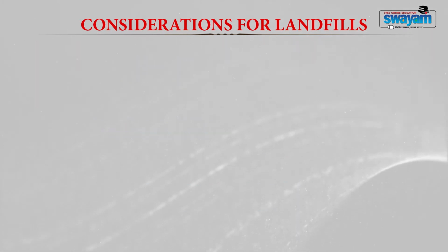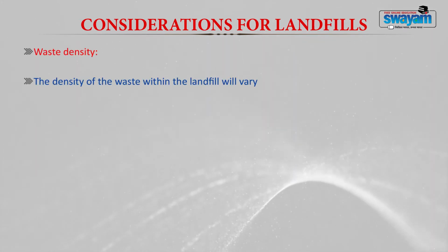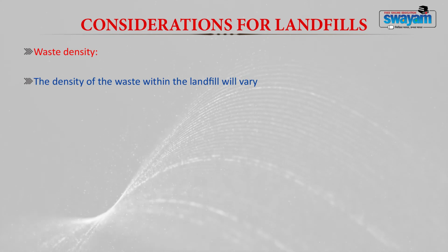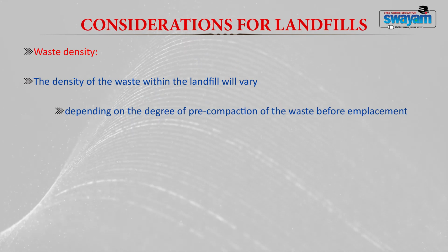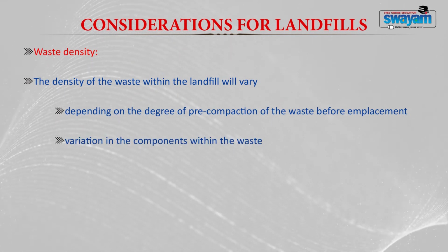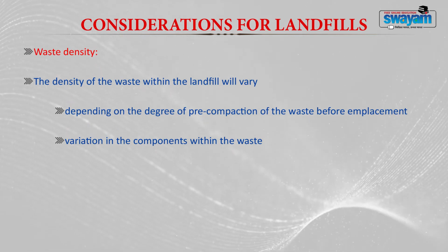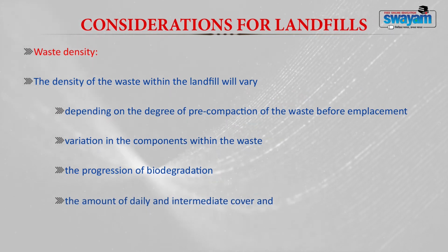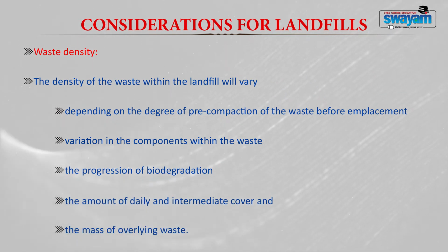The second consideration is your waste density. The density of waste within the landfill keeps varying due to various factors: 1. The degree of pre-compaction of the waste before emplacement. The variation also occurs in the components within the waste. Then the progression of degradation, the amount of daily and intermediate cover, and the mass of overlying waste. All these factors determine the waste settlement in a landfill. The degree of pre-compaction of the waste influences the amount of waste to be loaded into the landfill. It also influences the amount of waste settlement in a landfill.